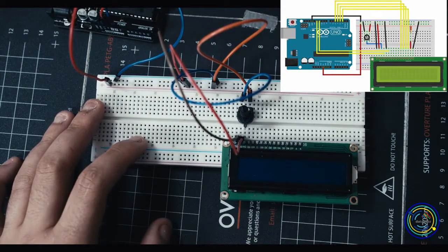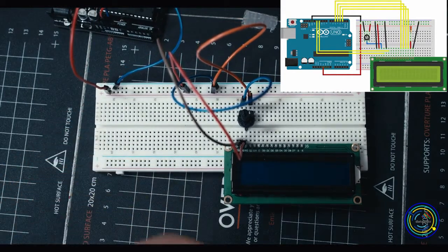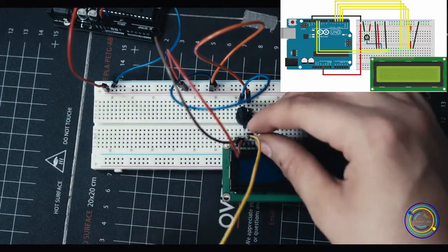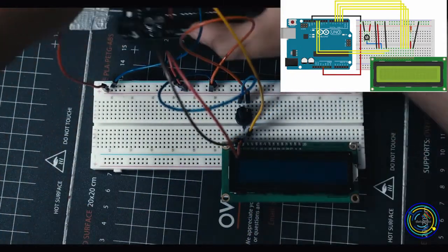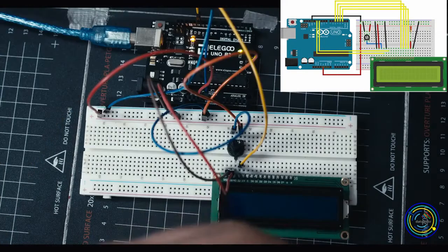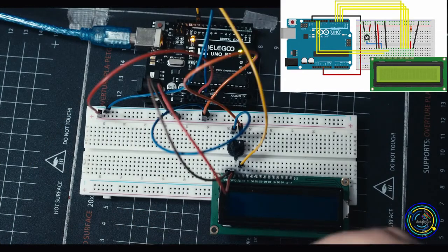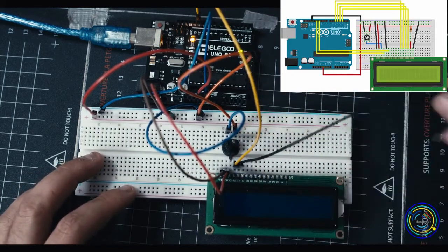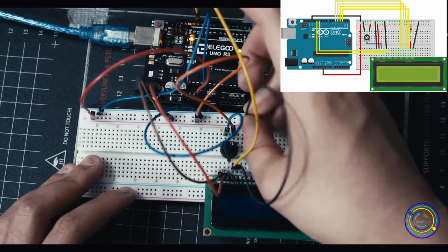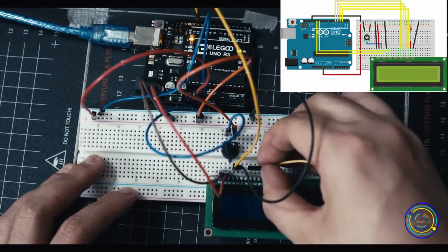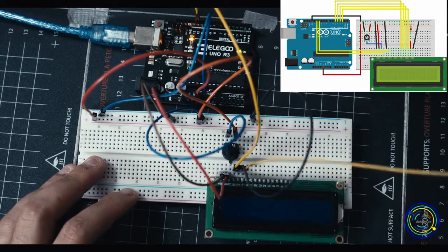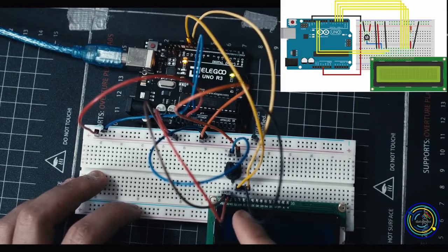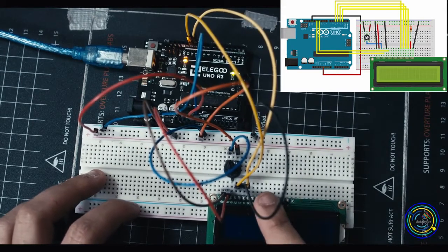Now, 1 over from that is going to be our 12 cable. So we're going to plug in 1 over, and we're going to send this to the 12 on the Arduino. Now the next one over is a ground cable. So plug this in right next to that first yellow one and send it to the ground. Now we're going to go to the next one over from that black one and plug that into 11 on the Arduino. So we go yellow to 12, black to ground, yellow to 11.